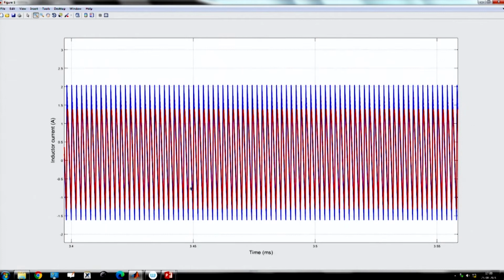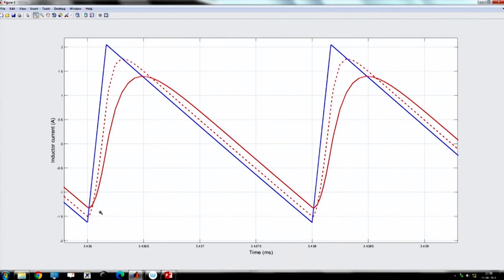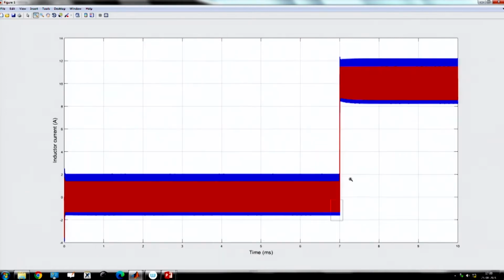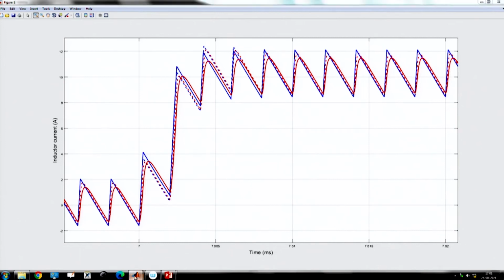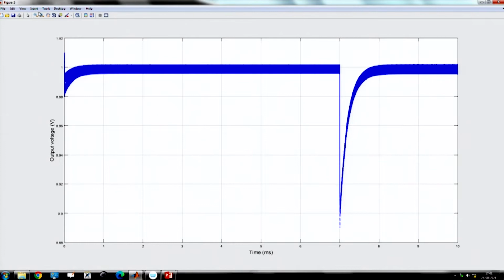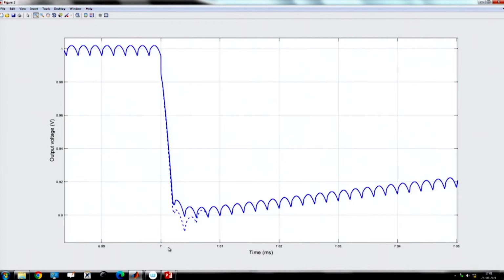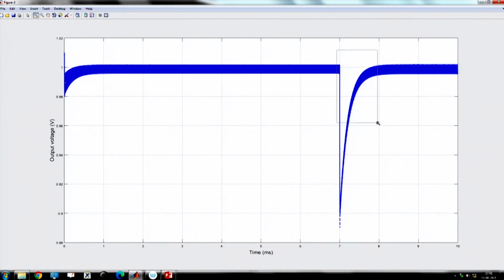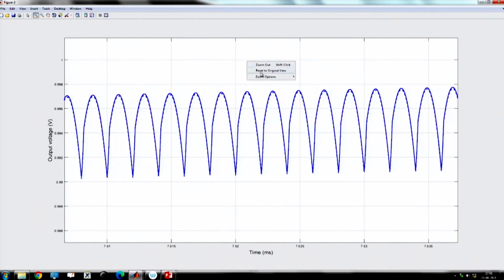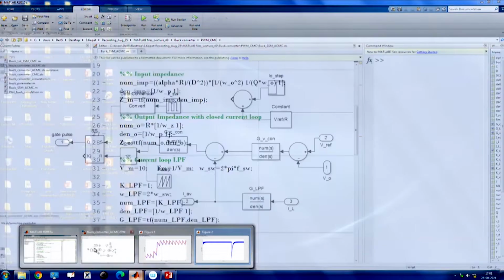You can see the solid line, which further reduces, that means your bandwidth is reduced further, and your response still is not drastically affected, but yes, somewhat it is affected, and this will be reflected in the undershoot of the output voltage. That means you see the output voltage, okay. So, the speed of the response will be affected, but not very drastically, because your voltage loop bandwidth is already slow, not very high.